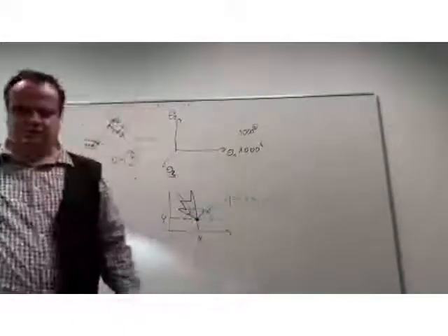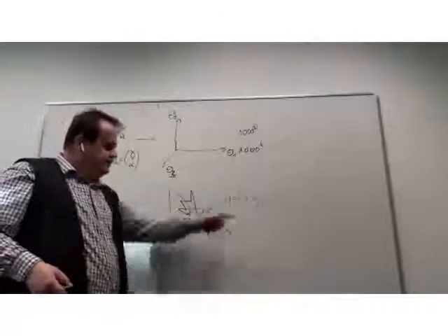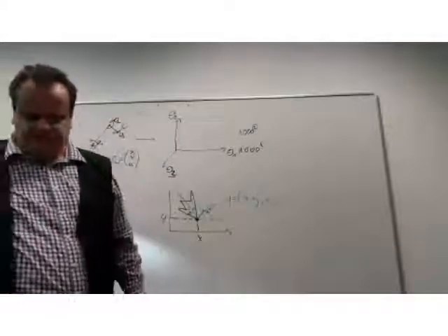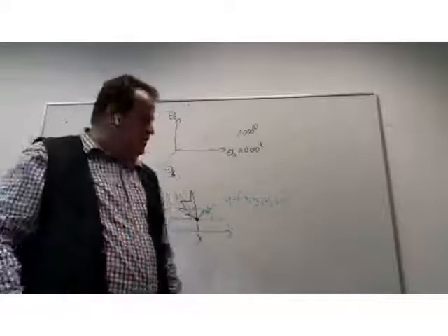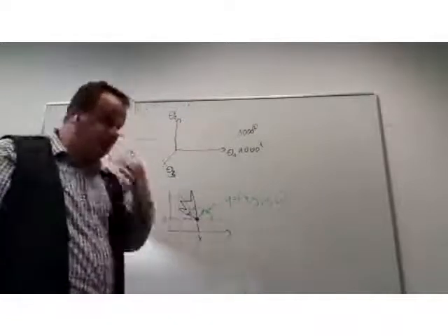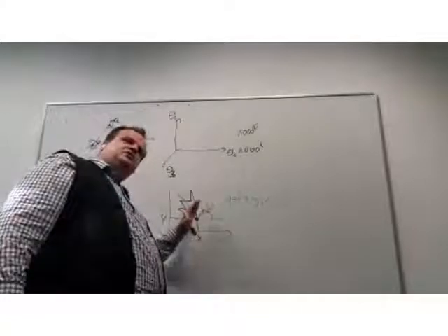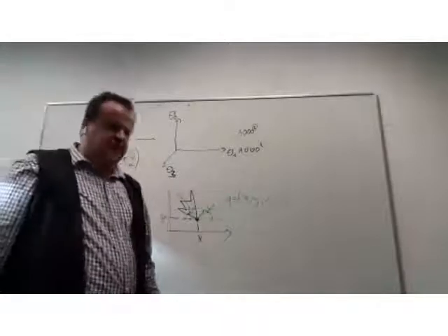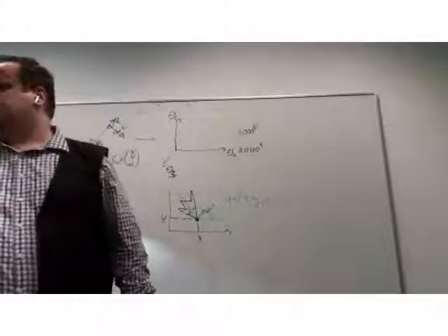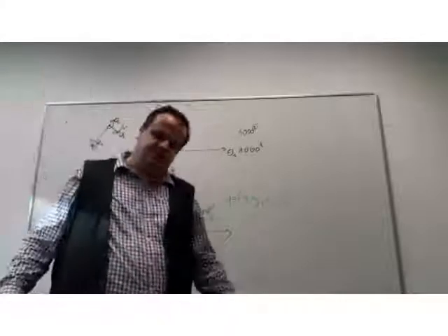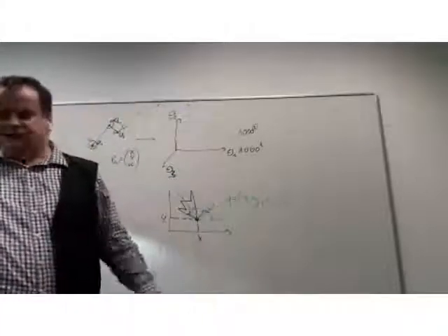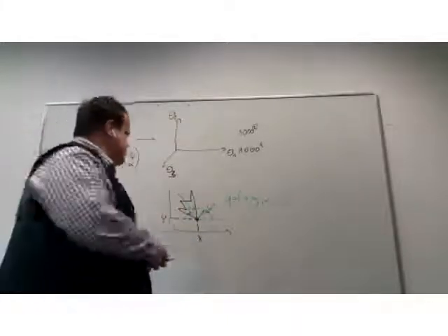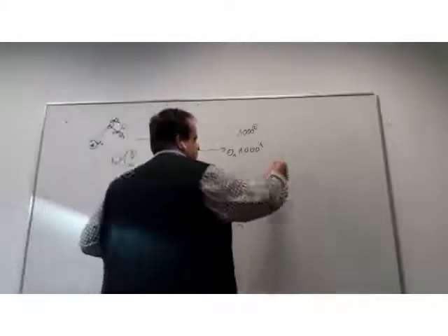It's a bigger representation, but suddenly we have 4 elements instead of 3. What's happening is you see here on the top, the u and v are not independent parameters. If I change the orientation of u, I change also the orientation of v, and it's simply expressed with the cosine and sine of the angle. So the minimum representation of such a structure is x, y, theta, and we should really make sure that we use the minimum representation.